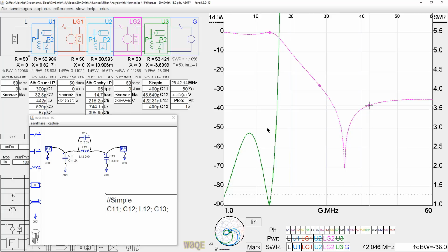Now, the rules do not require us to have 100% of the rejection be done in the filter. The amplifier is capable of being clean enough to not even need an output filter. So if we assume, and it's a fairly typical, fairly good assumption, that the second harmonic on a solid-state amplifier, due to the symmetry in the typical topologies we see in LDMOS amplifiers, should probably be down 20 dB easily. So if it's down 20 dB, and we get 27 more in our filter, we're at, say, 47 plus dB down, and that beats the requirements by 4 dB. That might not be adequate enough, but this is a fairly simple circuit.